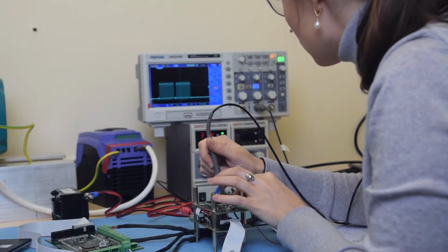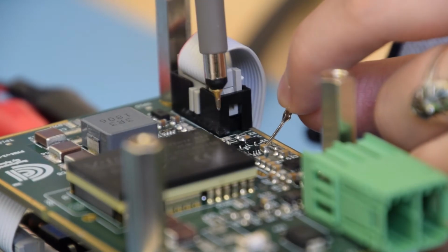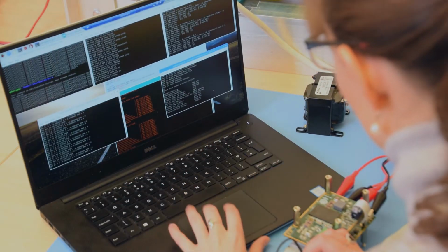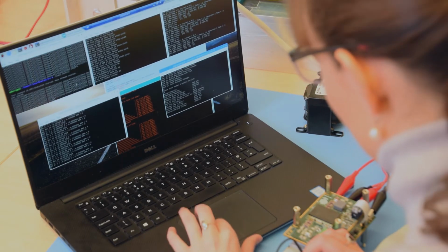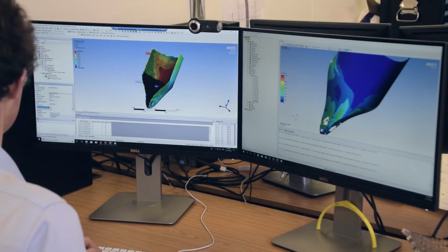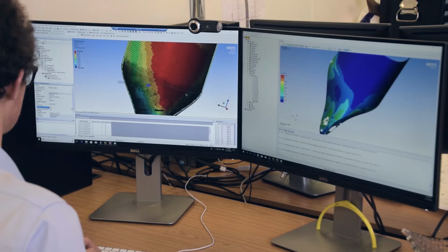The CCell device comprises a number of different systems: the prime mover, the power takeoff system, and the control system, all of which impact the loading on the structure and the energy conversion. We needed a workflow that could encompass all of this and provide the design team with key insights into the system interdependencies. Our CFD simulations now incorporate a realistic representation of the hydraulics and are also coupled with an open source finite element modelling package. This has greatly sped up the optimization of CCell and helped get our pilot deployment in the water.